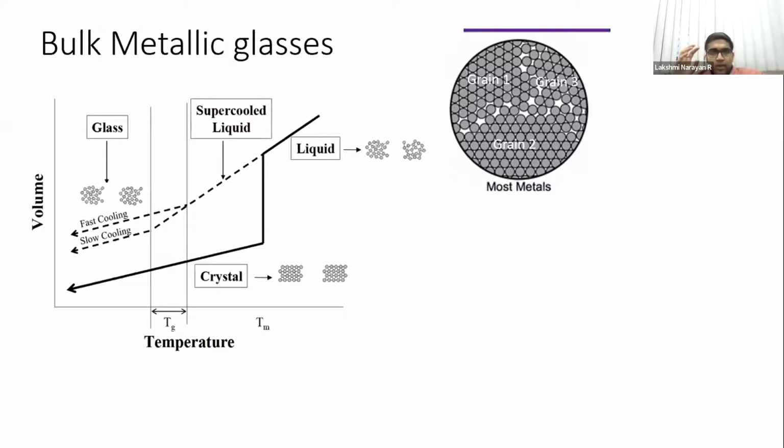They found that the amorphous atomic structure of the liquid in a metal can be maintained if you cool rapidly enough. Okay. And he also found that the faster you go, the more you preserve the randomness, and you actually bypass the nucleation event. So you're able to solidify a structure which is very amorphous, or rather retains the memory of the liquid structure even at room temperature.